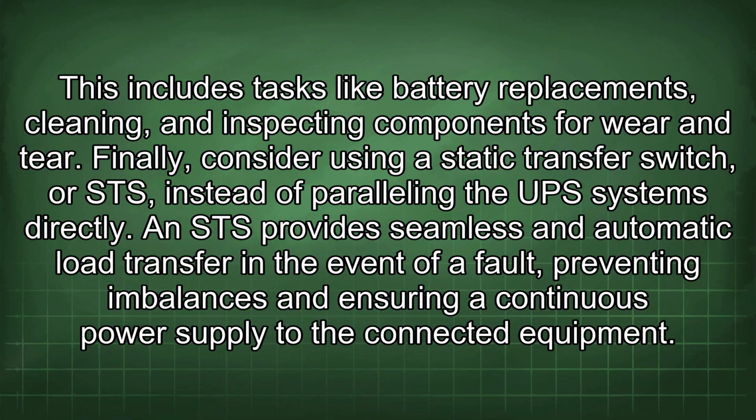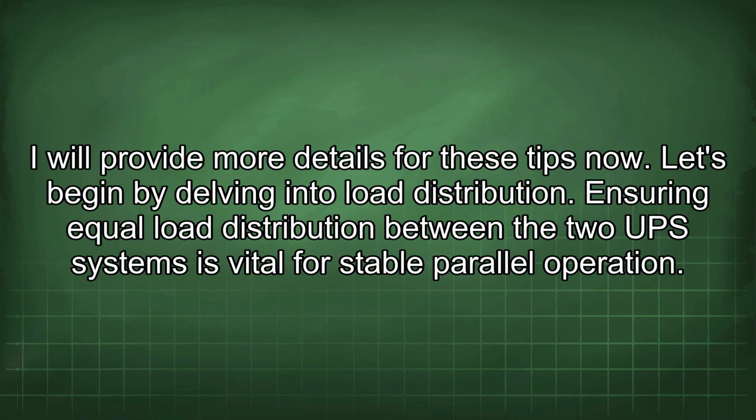Finally, consider using a static transfer switch, or STS, instead of paralleling the UPS systems directly. An STS provides seamless and automatic load transfer in the event of a fault, preventing imbalances and ensuring a continuous power supply to the connected equipment. I will provide more details for these tips now. Let's begin by delving into load distribution.